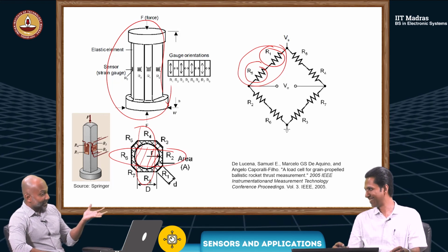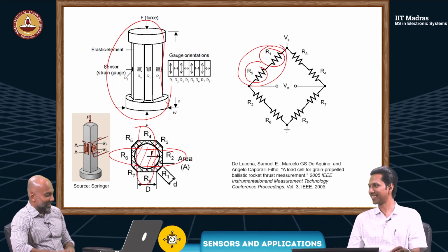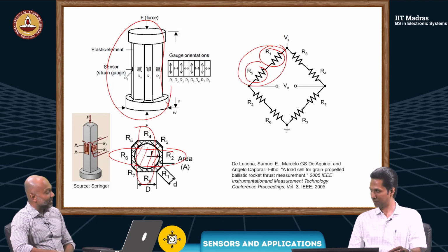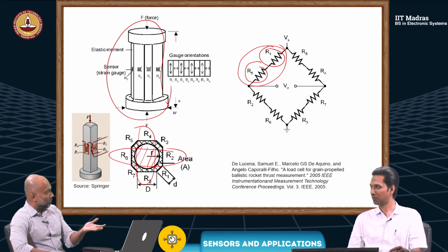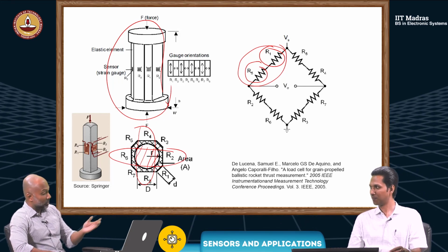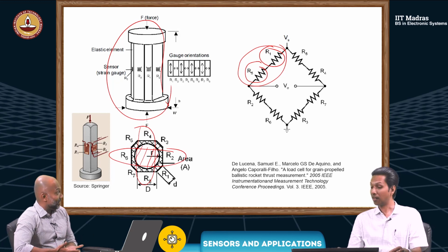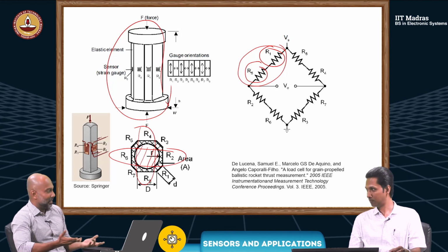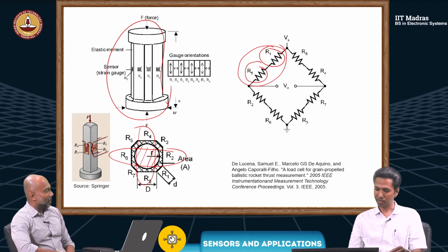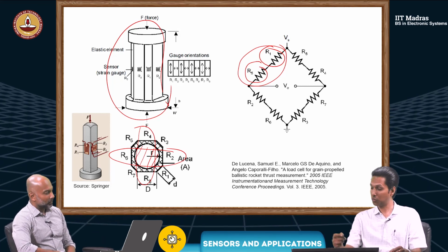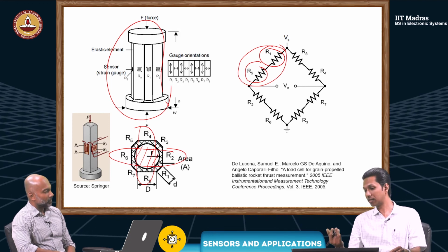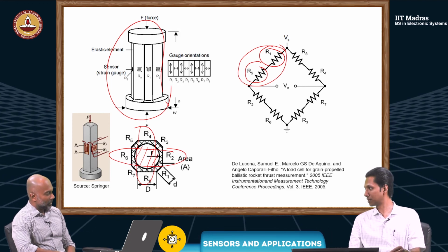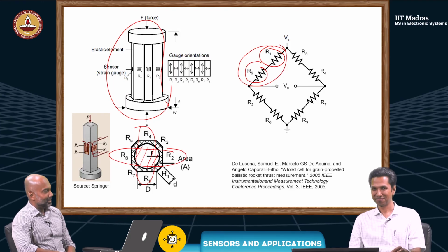Exactly. I think that's the beautiful thing about strain gauges, right? You can attach them to these kinds of structures. And you also said with the Wheatstone bridge, just the other day, you mentioned the temperature compensation. Correct. Right. Again, with these having the alpha. Yeah. Then you don't have to worry about the temperature. Exactly. Same applies here. Since you have the full bridge, it's insensitive to change in temperature. Very nice.